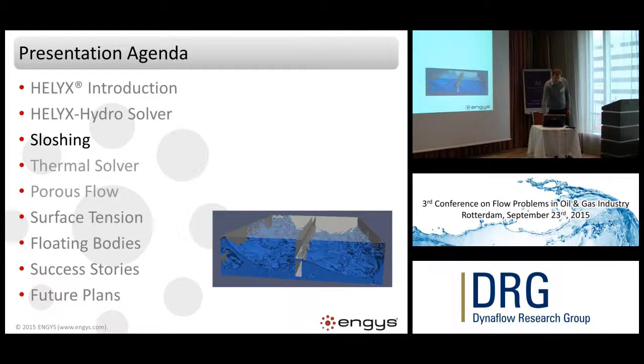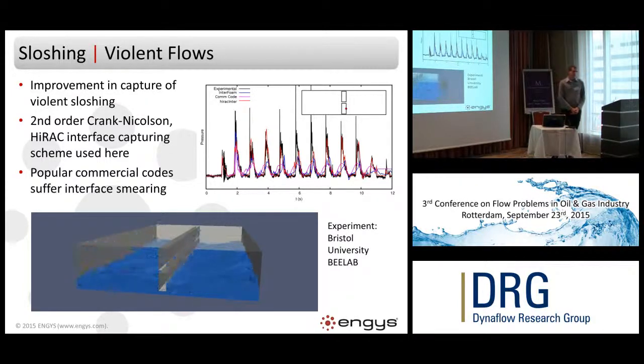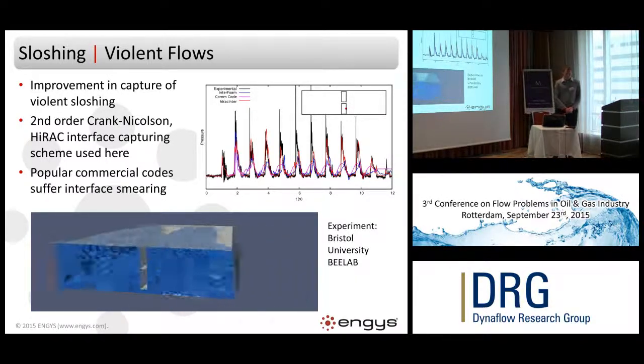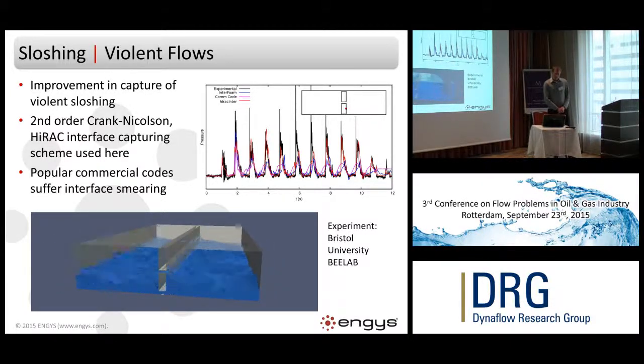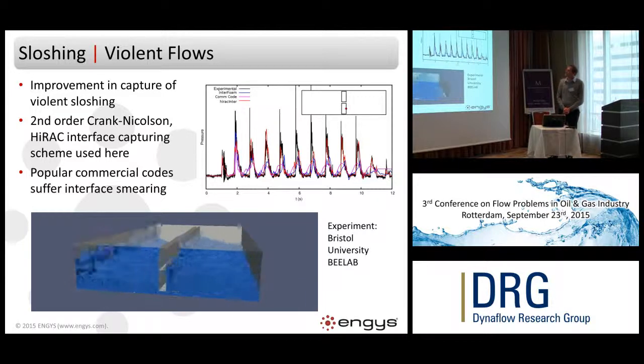So first of all, just to focus a bit on sloshing type of applications. Some improvements that are important here are an improved interface capturing scheme, a higher fidelity one that is fully second order accurate, and an improved pressure interpolation scheme. You can see on this graph an output from a pressure tap inside this shaking tank case.